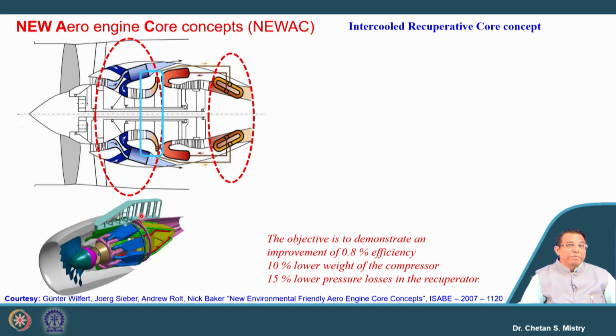Parallelly, we have discussed the limitations of the centrifugal compressor. Say entry of the flow is axial and exit coming out from this centrifugal compressor is radial. So you need to have a specific device or diffusing device which will be guiding the flow in axial direction. But here it is reverse flow kind of configuration we have for the combustion chamber, and this design has purposefully been done. Here if you look at, it is using the piping for say recuperative kind of configuration.